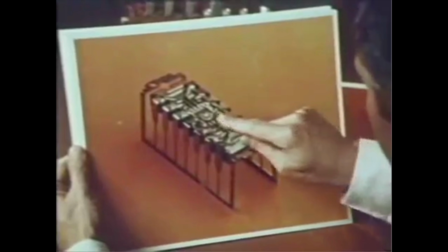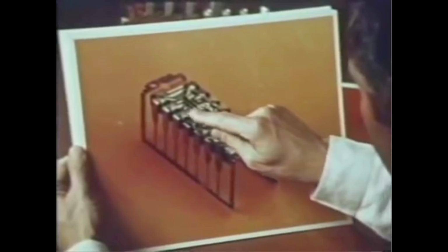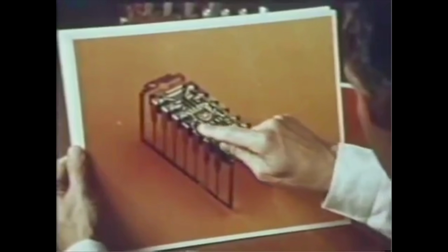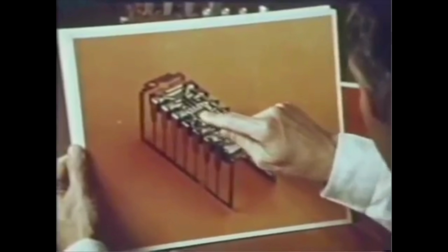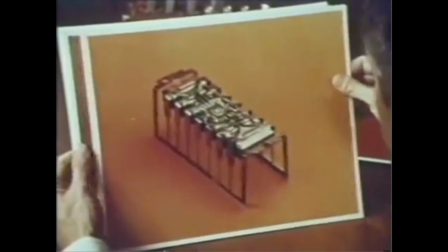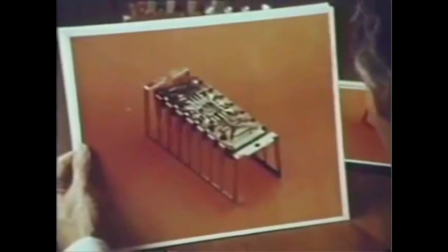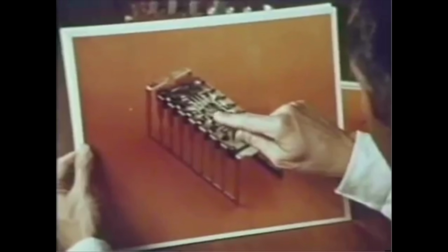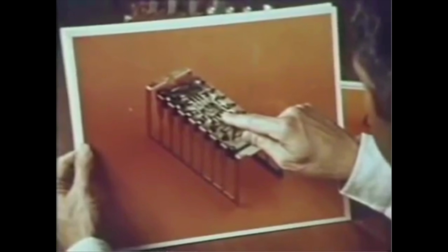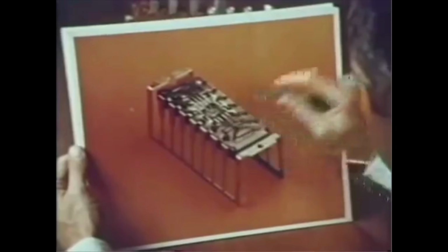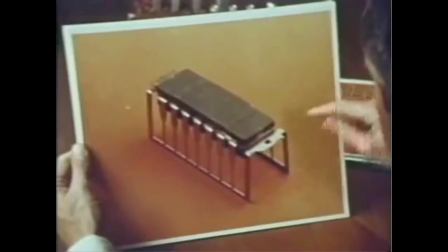And here is the arrangement. Chip in center, Kovar frame around the outside, and notice that the tips of the frame here have been metallized. This will form the connection to the chip directly. As shown here, where the lead bond wires have been placed connecting the pads on the chip to the metallized tips of the Kovar frame. We complete the sandwich by putting the top half of the package right on top of the frame.